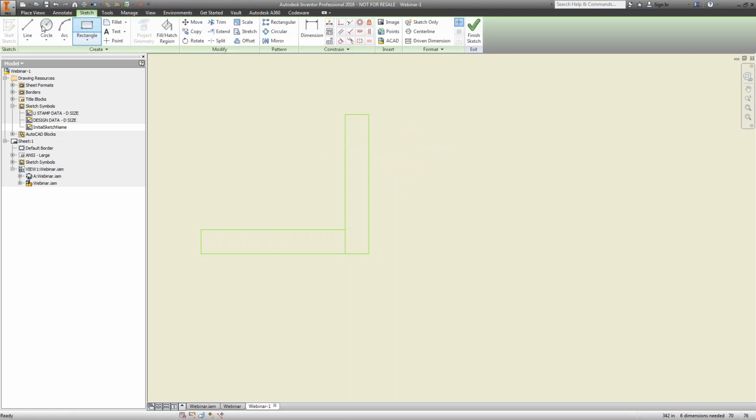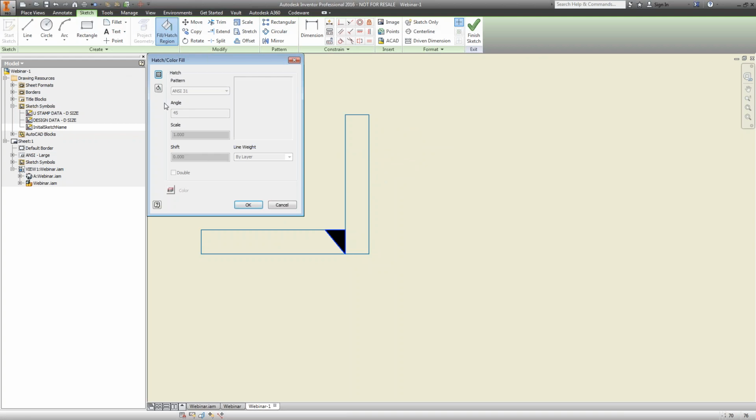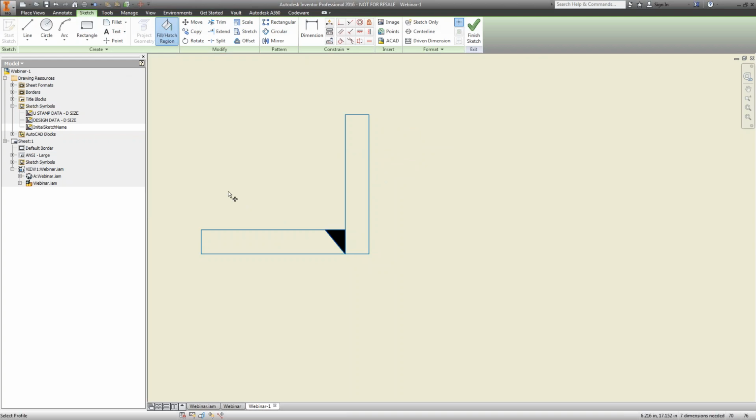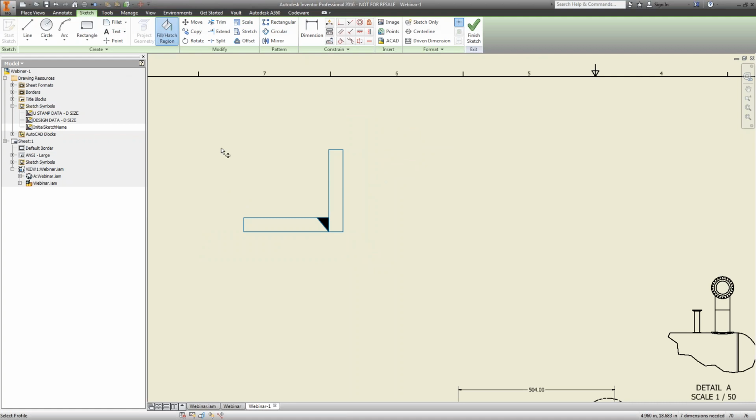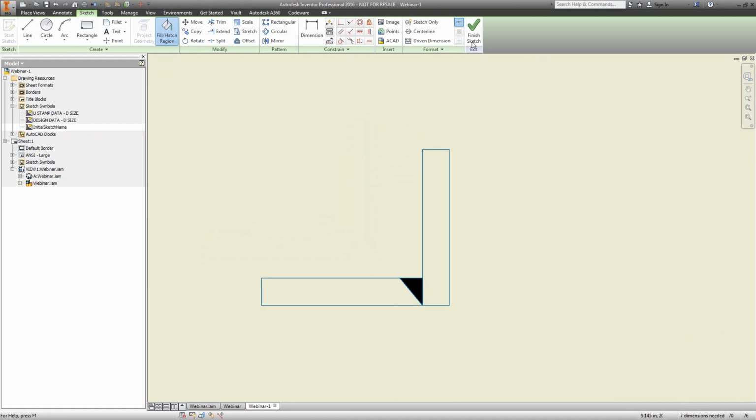And then you can also put your fillet weld in here, like so. That could be something that you want to call out on a drawing. The majority of nozzles would have this type of configuration with your full penetration weld. You could put the sizes on there, things like that. Then when you click Finish Sketch, you simply name it what you want.